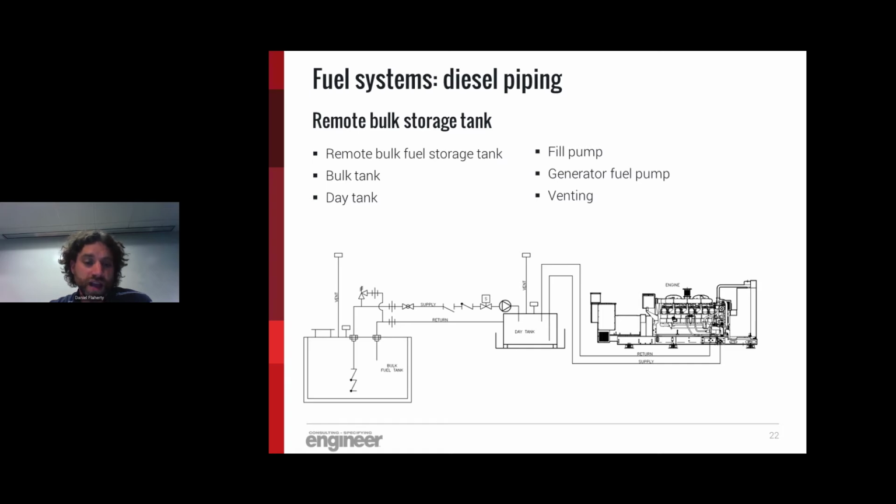Whatever fuel the engine does not use, it will put back into the day tank, which is located very close by. So you don't have to worry too much about overcoming system pressure losses. However, when considering the design of these systems, you have to run your hydraulic calculations on them.